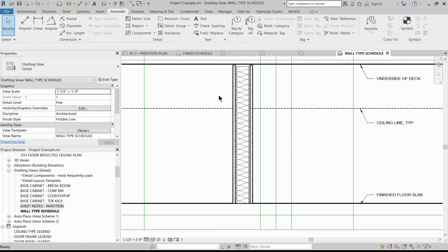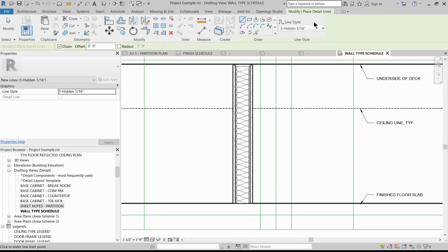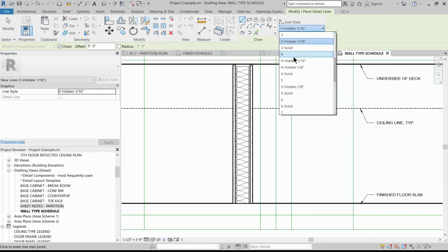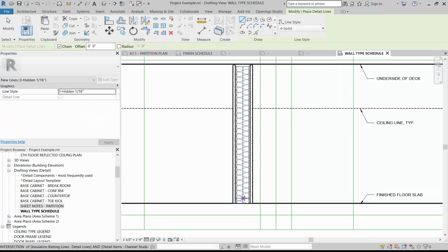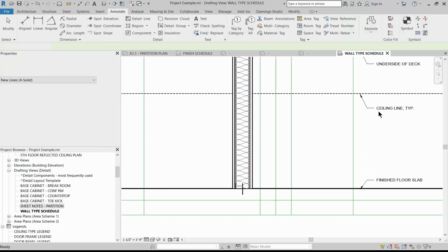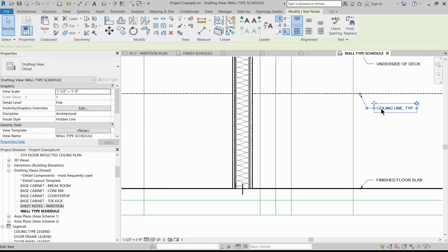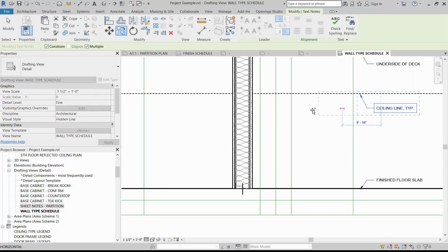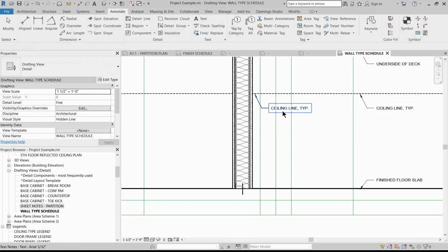And then finally, don't forget using detail lines to show the attachment points. So I'm showing that I have anchorage on top, and then I'm attaching directly. So anchorage to bottom and anchorage directly to the top. So this was just one partition, and this was live, so this goes pretty quickly once you have all of the components. And then copy over your text.